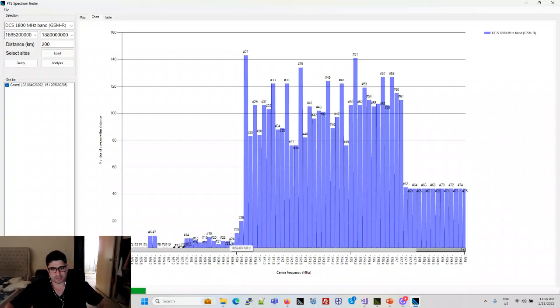Because you can reuse the frequency in the case of GSMR. So it has been really underutilized, maybe for a very good reason, because these are maybe used for the pilots or a specific network, something like that. But you can see from 27 up to 61, they have been used more than 80 times, because each tower would have maybe 4 to 8 channels, depending on traffic demands. So you can see they have been really well utilized. This is how often a channel is used, so it gives you a perspective into the efficiency of the frequency allocation.